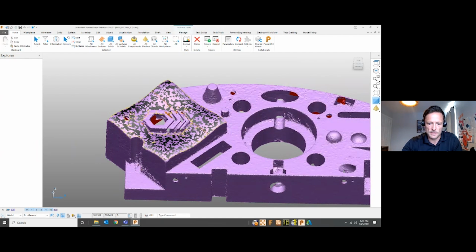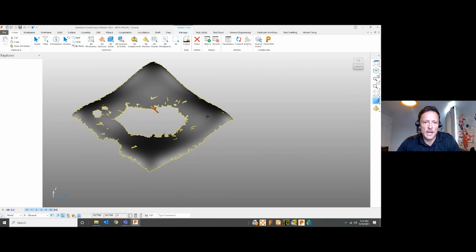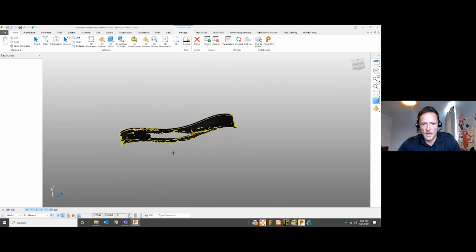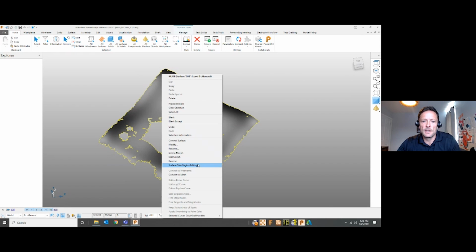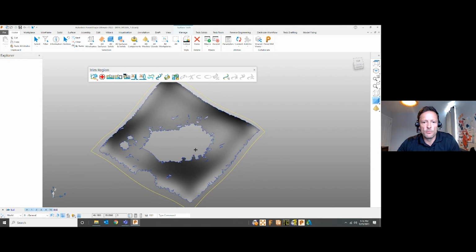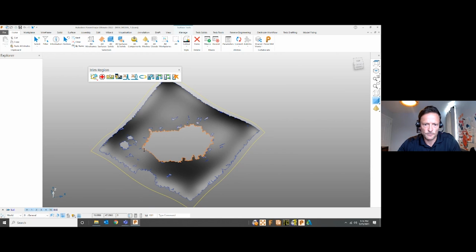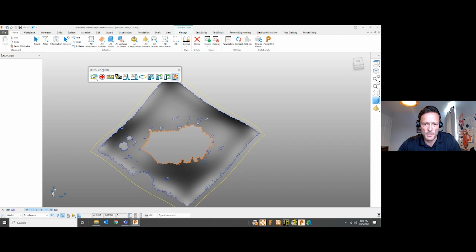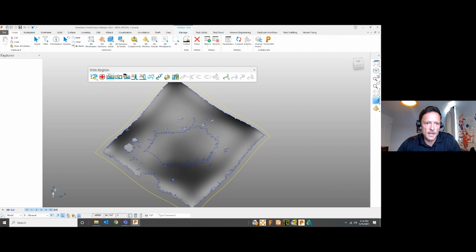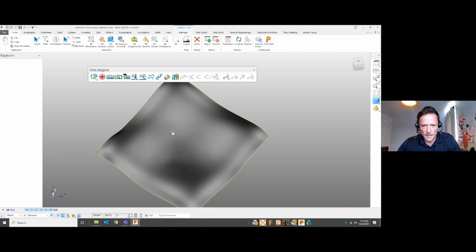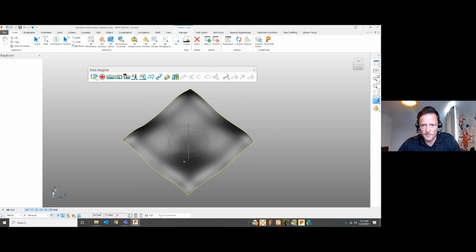If I go ahead and pick that surface, what we can see there, it's actually like a trimmed NURB surface. So I don't really want that. But what we can do is analyze what we call the trim region editing, or the boundaries or the intersection curves. If I wanted to, I could go ahead and delete these individually. But really, if I select all of the P curves, so again, I can just say select all P curves, get rid of them. That's going to leave me like the original surface shape.